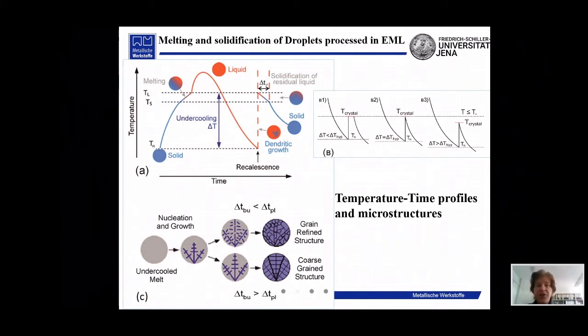So, if the initial starting undercooling from TL, defined by TL minus TN, is smaller than the hypercooling limit, then we have this scheme. We heat up to a temperature around the liquidus temperature and then stay at the plateau several milliseconds or seconds or even 1 minute, and then cool down. It depends on the cooling rate of our cooling gas. And once again, hypercooling is a parameter which gives us the ability to estimate the adiabatic temperature of solidification. So hypercooling is equal to the adiabatic temperature of solidification.